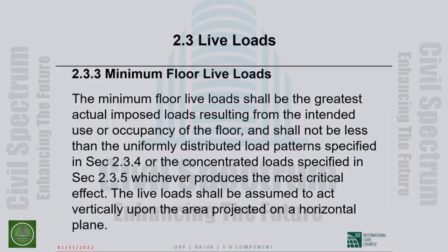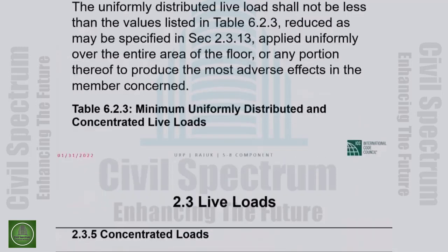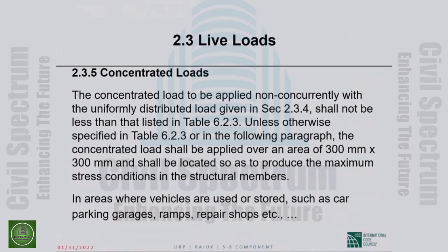The live load shall be assumed to act vertically upon the area projected on a horizontal plane. This is also important. Okay. So this is vertically on the horizontal projection. That's how live loads are always applied. Uniformly distributed loads are in the table 6.2.3. Concentrated loads are also in the same table, 6.2.3.